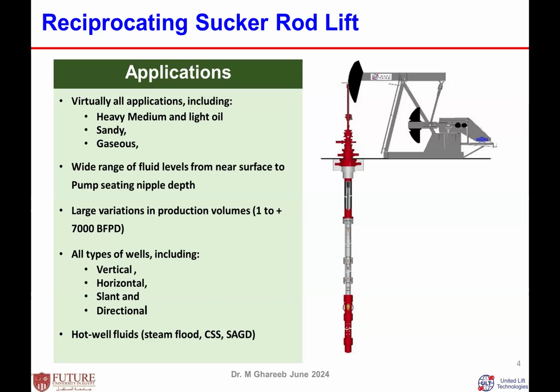Once the fluid has reached the downhole pump level, even if it is only 1-2 feet above the pump, the pump can lift that fluid. Even if the fluid level reaches the surface, it is no problem, and the pump doesn't care. It is a reciprocating, positive displacement type of pump.